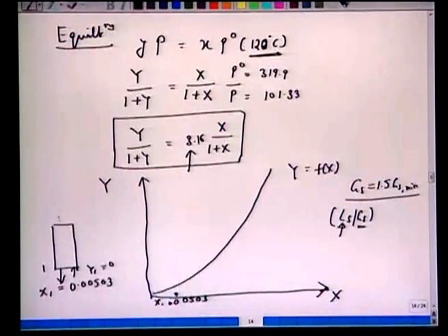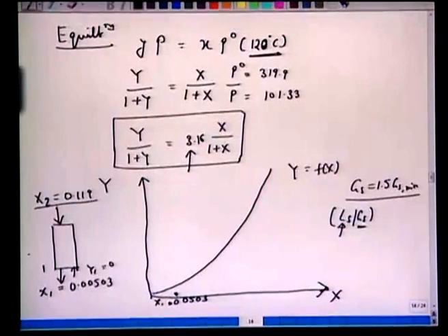We know the concentration here. Now this is x2, and this x2 is 0.119. This concentration is the same as the concentration of the spent liquor from the column 1 absorption column. So we can mark this x2 as 0.119. Just compare again: earlier we used to mark y2 here because that was the absorption column, those were the conditions given to us.